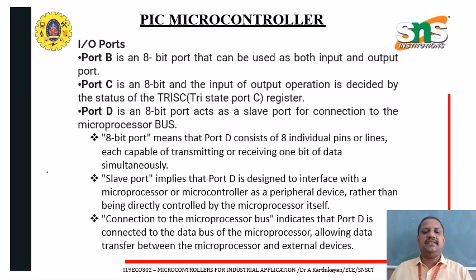And port B is an 8-bit port. It can be used as both an input and output port. And port C is also 8-bit, and its operations are decided by the status of the tri-state port C register.